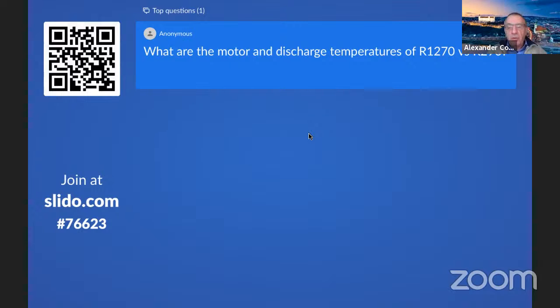What is the recommended superheat for these refrigerants? I think very similar to propane, because propane is a very cold refrigerant in terms of the internal thermomap of the compressor. So the delta between propylene and propane is not so dramatic that it should lead to a reduction of superheat.